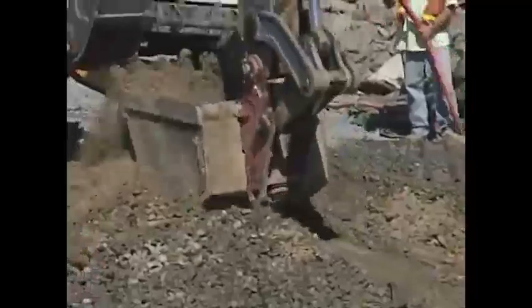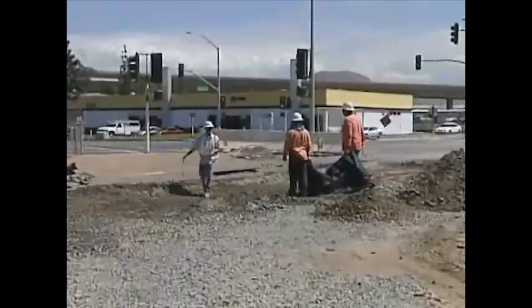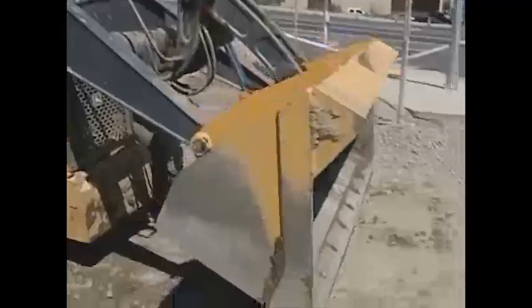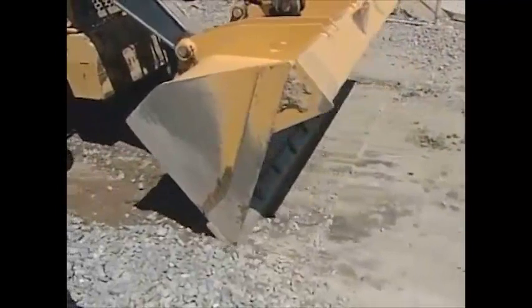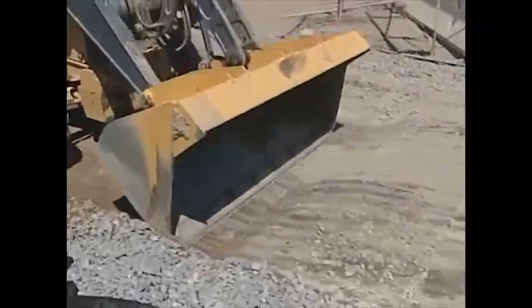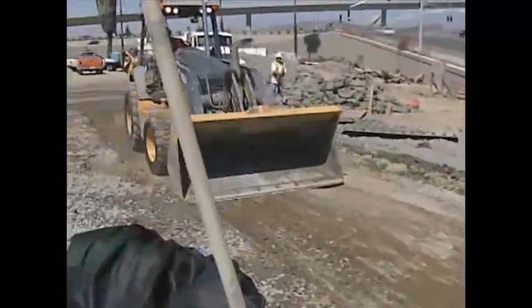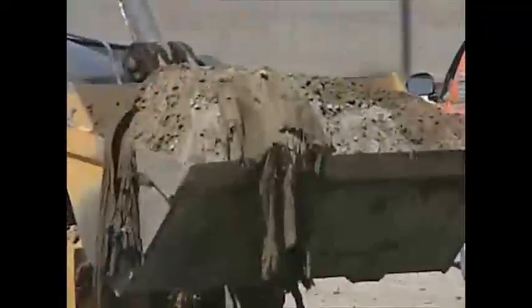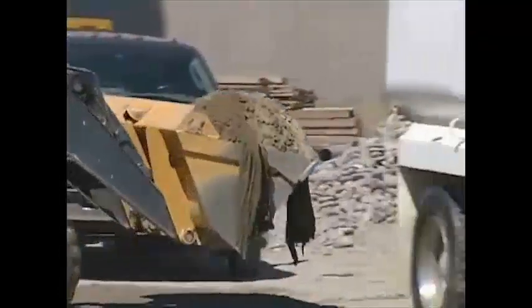Excavate the area to a depth of 12 inches, unless otherwise specified by a soils engineer. Also, grade the construction entrance point to prevent runoff from leaving the site. Runoff must also be routed from the stabilized entrance to a sediment trapping device before discharge. Then, make sure the area is cleared of all trash and debris.